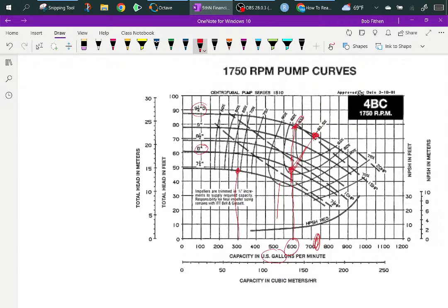Yeah. So there's an art to picking these pumps, and that's why near the end I cover pump curves and how to go through them. That's referring to the head, and these are the back stuff. Yeah, in other words, this thing, it'd be either meters or feet, but this thing could pump up to 70, 80. Say you bought this one, it could pump water up that high. So it can pump it vertically that high? Yeah.